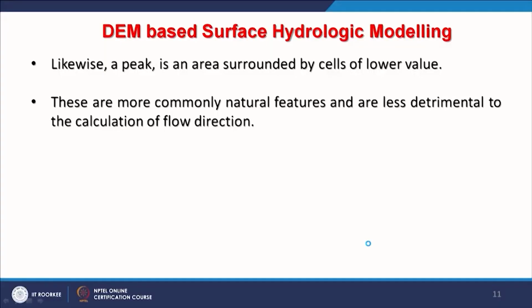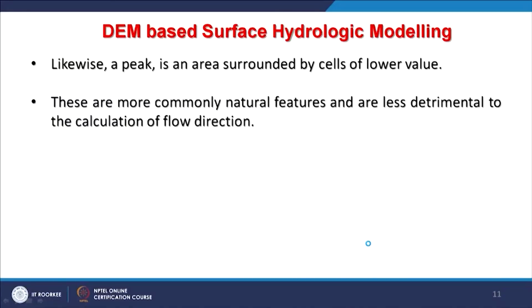Even if it is not being fulfilled, still we can exploit it and see how it affects the groundwater, which we will discuss a little later. Similarly, when we identify sinks, we also identify peaks, but peaks will not affect much in that way. But nonetheless, in that process everything is identified, and then it is made sure that whatever water is dropping on the surface in a watershed has to come out of the outlet.